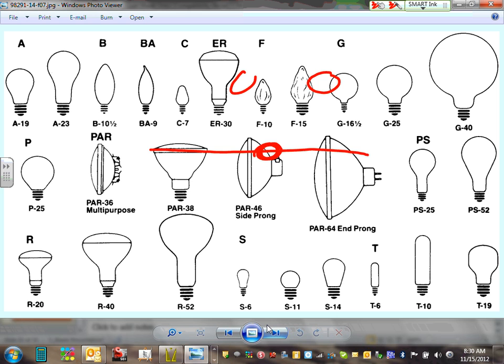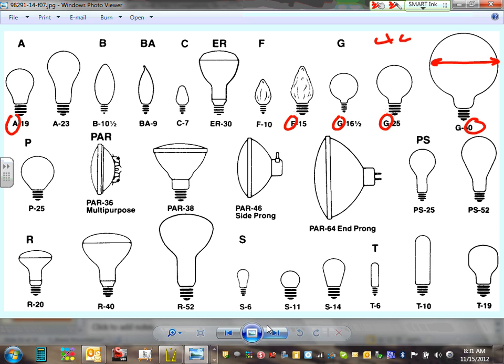So that's for incandescent lamps and a lot of lamps. I'm not going to sit and tell you guys about all the types of incandescent lamps that you can use. There's the P's, the A's, the C's. You can see they give them designation letters for different shapes. Look at this shape. This is the most common shape, A, right? One thing I want you guys to know, the number here is actually the diameter. So this number is 40 divided by 8, which is what? 5.